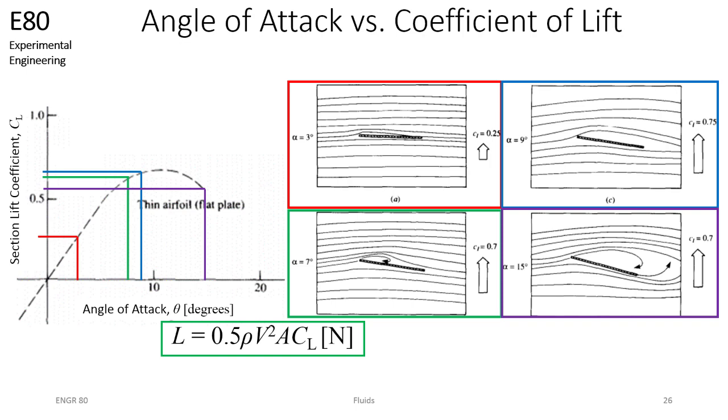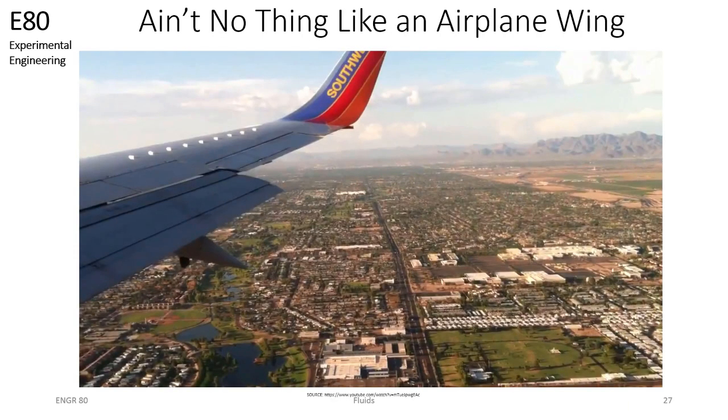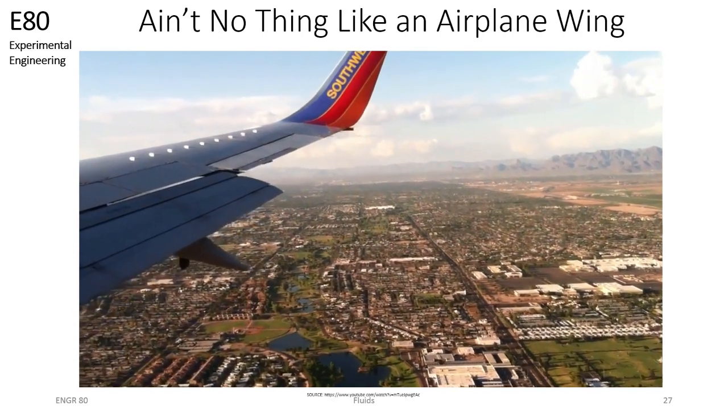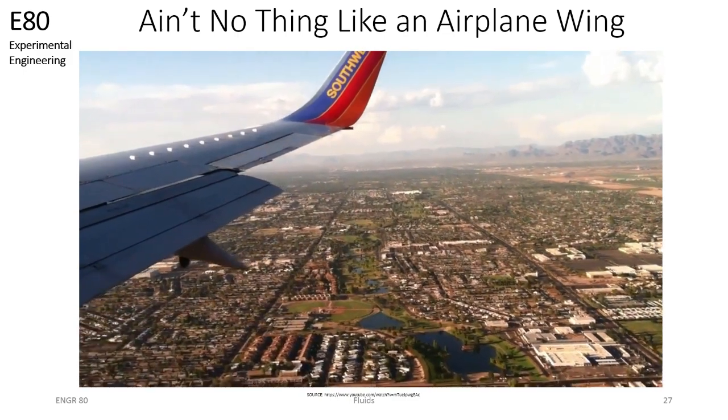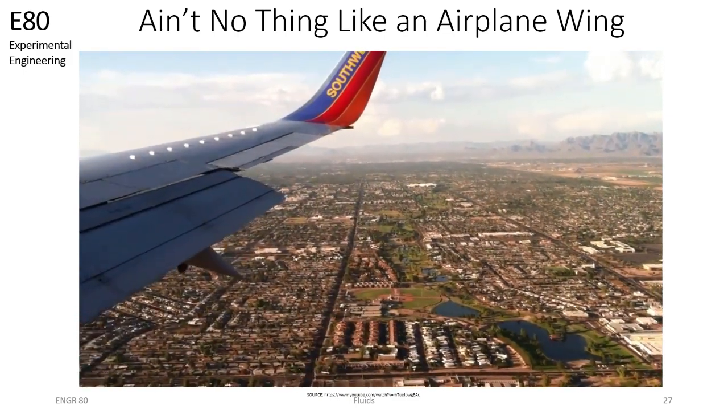Therefore, the lift coefficient, as well as the lift force, for a flat plate is maximized at an angle of attack of about 11 degrees. Maximizing the coefficient of lift at low speeds is the reason why airplane wings change form during landing.